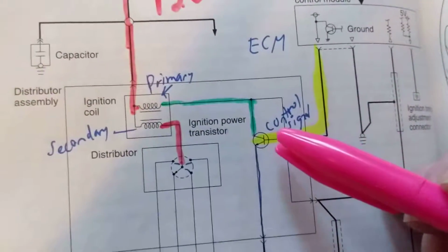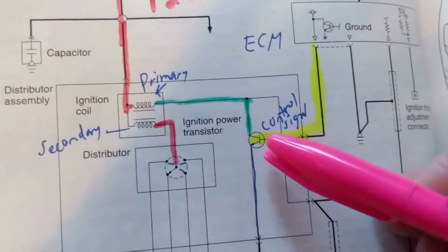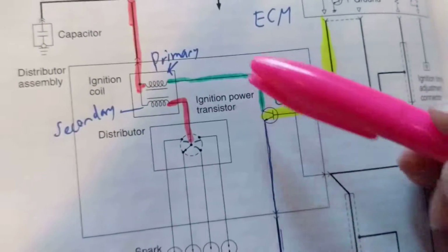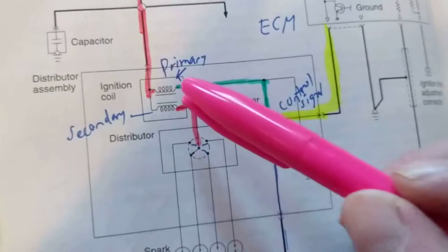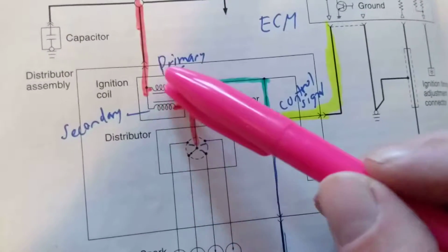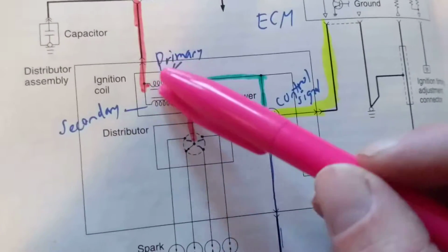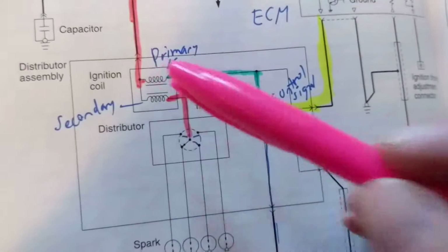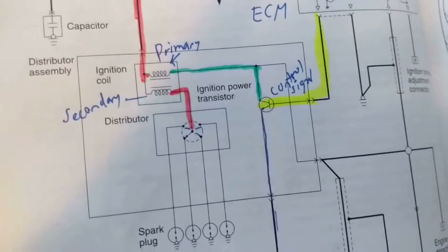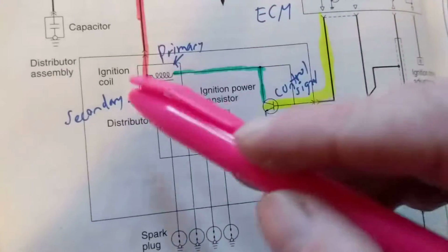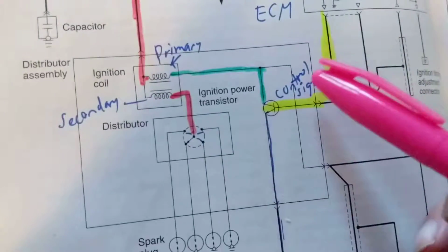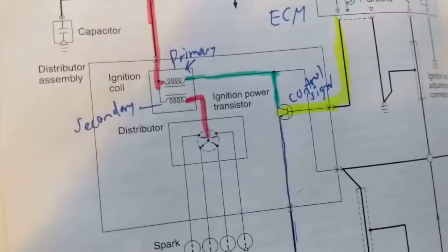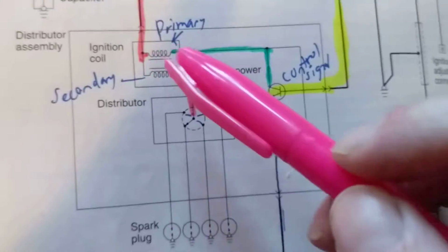The control signal will turn off the transistor. When you turn off this transistor, or a switch, like we want to call it, current cannot flow. But the magnetic field in it will grow to a certain limited amount. So the current goes in it, flows through this, and now it's cut off. Boom. Now there's no switch to ground. This magnetic field collapses.